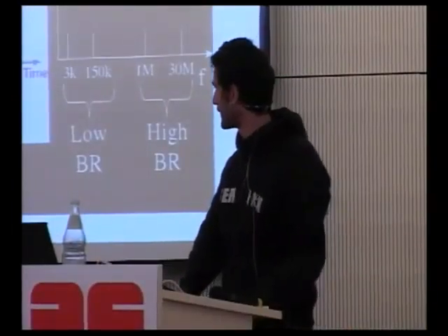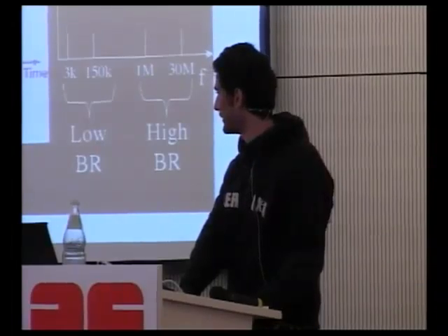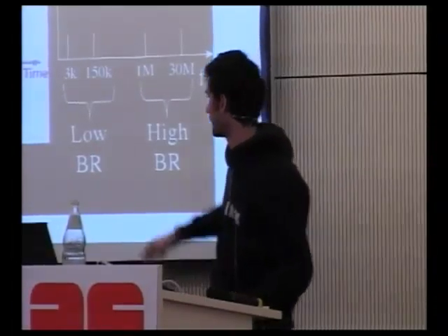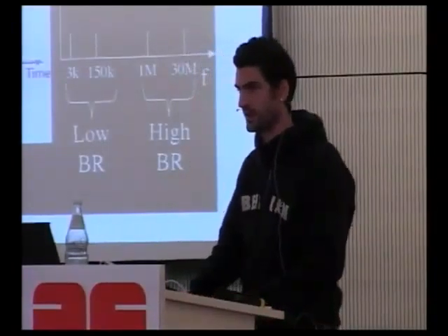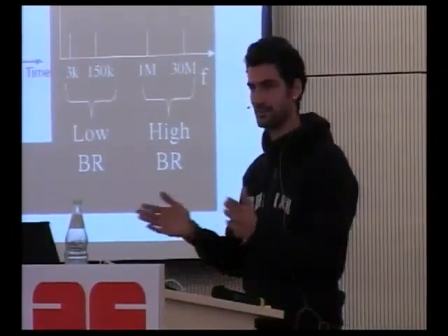And in light gray, you have some low bitrate power line. I'm sorry for the quality of the schematic. The low bitrate is using this band, which is 3 to 150 kilohertz, which holds less space for bandwidth and bitrates. So we will target high bitrates.